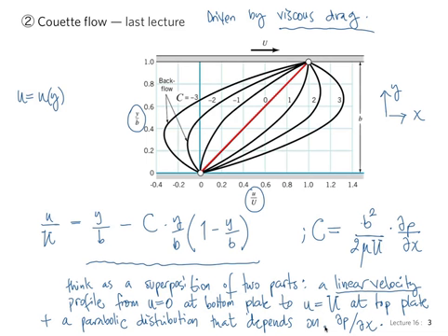If the pressure gradient is 0, the flow is still moving because of viscosity. In the previous example, where we had the flow between two parallel plates with the two plates stationary, if there's no pressure gradient, there's no flow because it's only driven by pressure. In this case, there is flow with no pressure gradient, but if you add a pressure gradient, that contributes, again, the parabolic component of velocity, if you will.